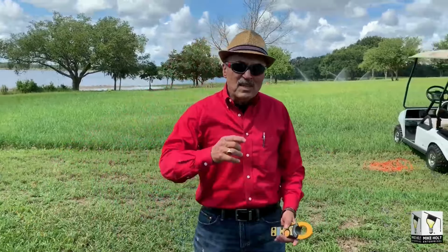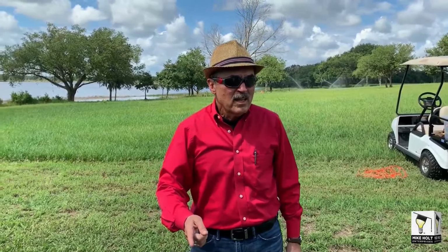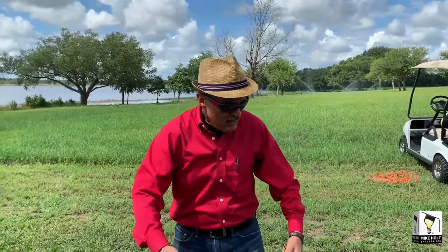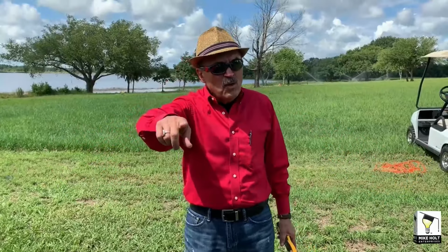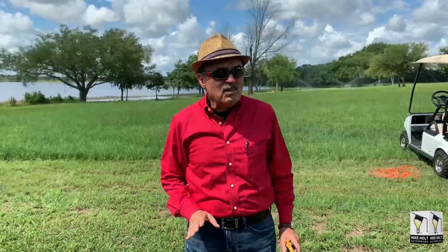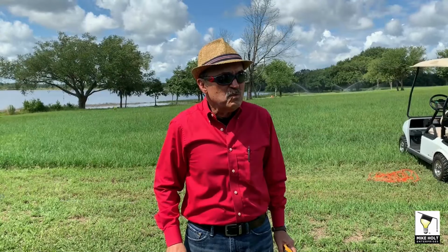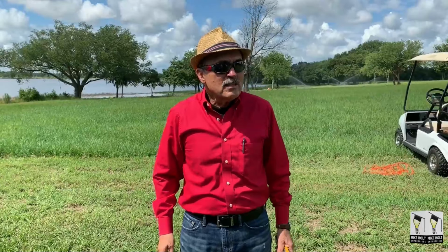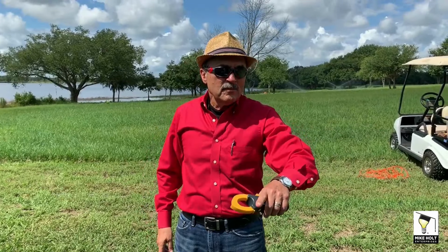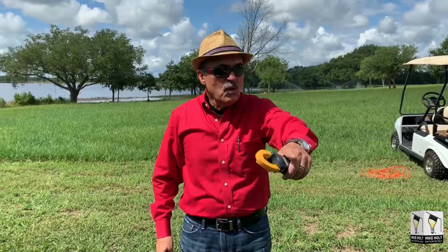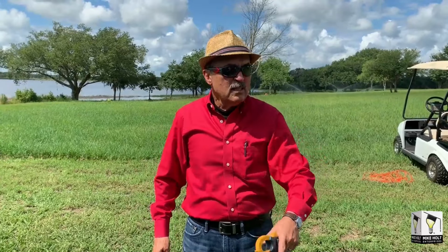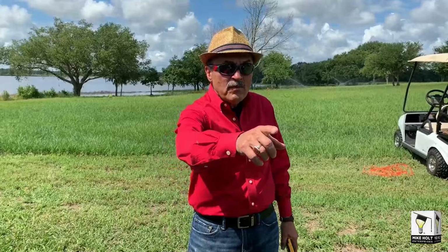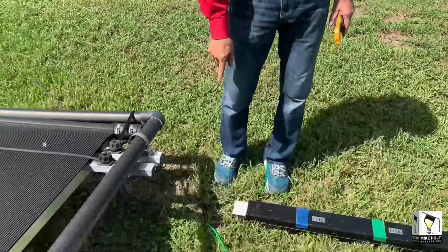So not only did we not clear a fault, but now we created a much greater area where you could get killed. See, if they brought no effective ground fault current path and they didn't ground it, where could you get killed? If you touched it. Because if that was energized with no effective ground fault current path and you don't clear it, which it is, and you touch that, you're going to get killed. But now that they ran a ground, we increased the area.